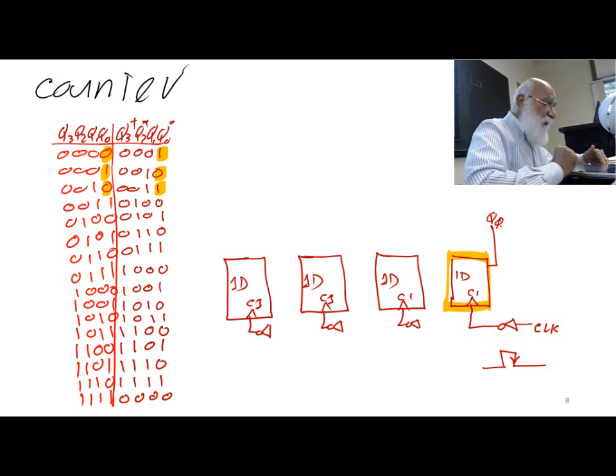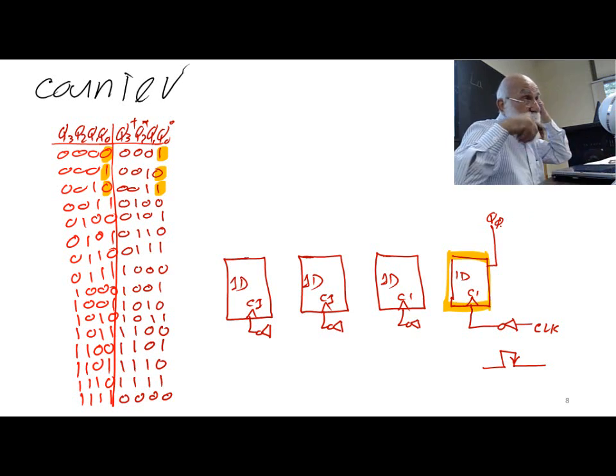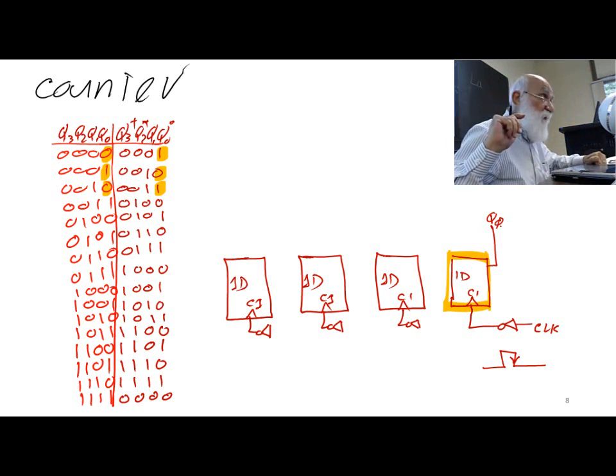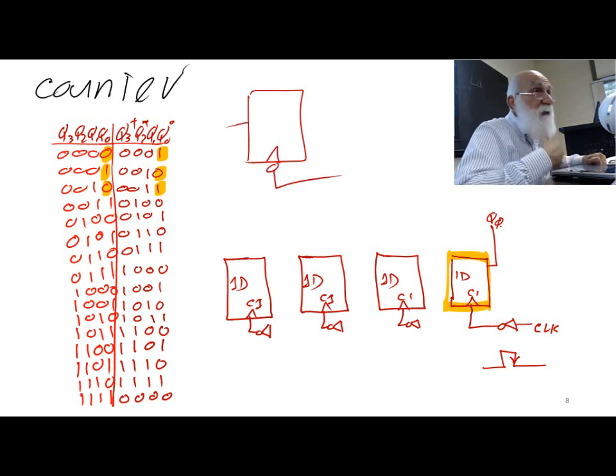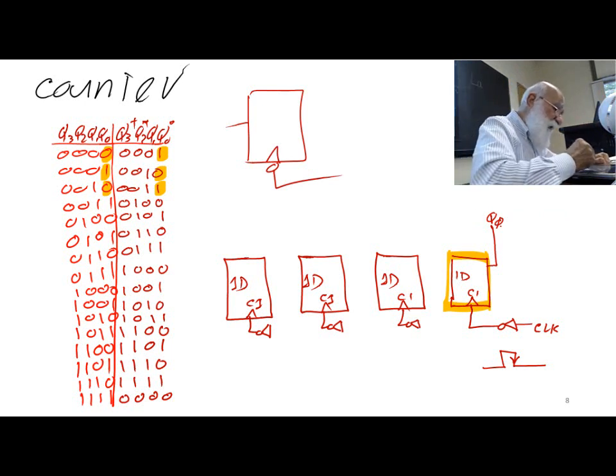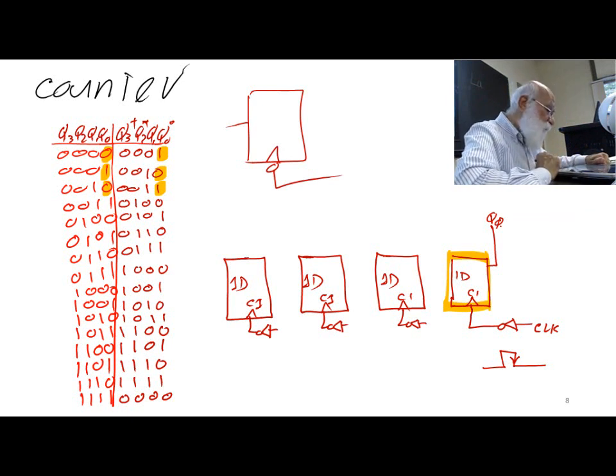But then I will either have an inverter put in there, or I just go grab a flip-flop with falling edge clock. If I put the inverter symbol, it means that I have a rising edge, I'm turning it into a falling edge. But if I use this symbol, it means that it is indeed a falling edge flip-flop. Do whichever you want, but in any case, I want the end effect to be that this is falling.